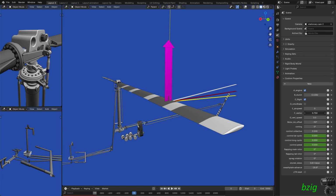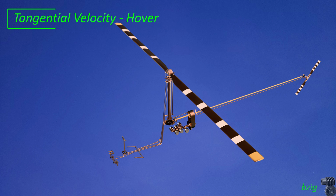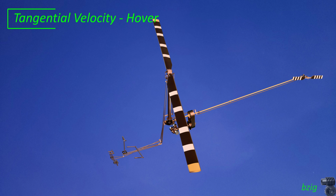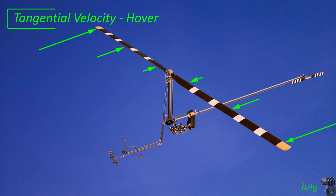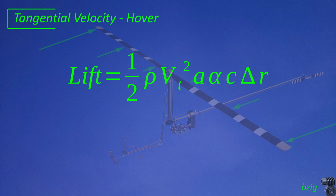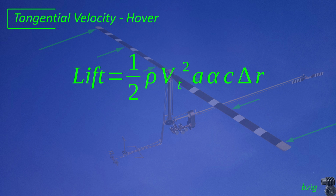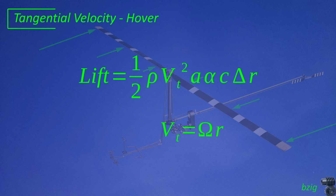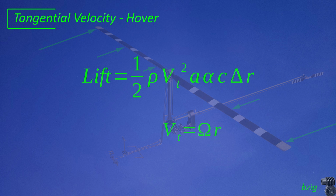In the simulation, the math is not discrete. It's continuously variable along the blade. And let's talk about this math, starting with tangential velocity. This is the air velocity in the plane of rotation that a helicopter generates by rotating its wings. Lift produced on the blade section is proportional to the square of this velocity's magnitude, and we calculate this velocity in a hover by multiplying rotation speed by the radial position of the blade element.